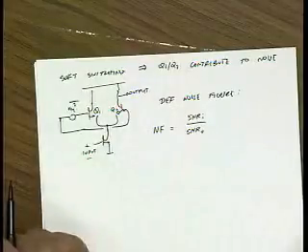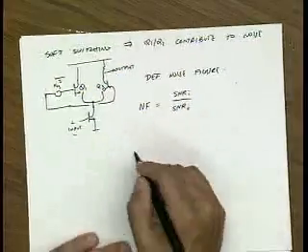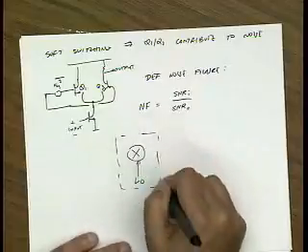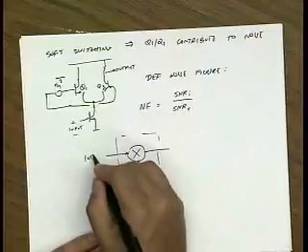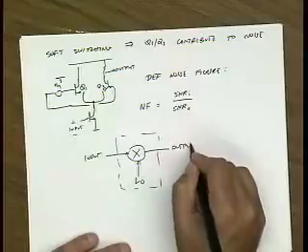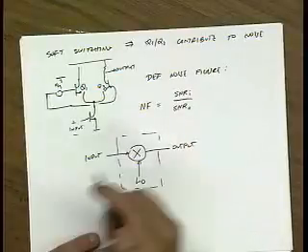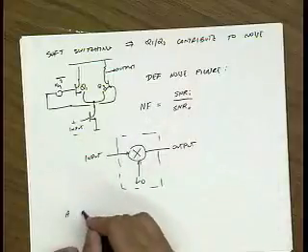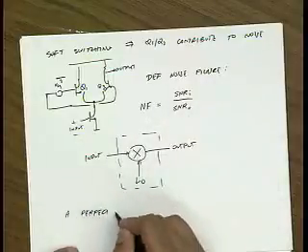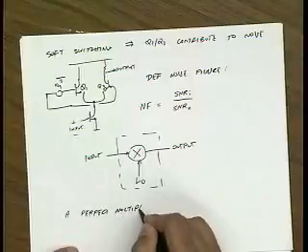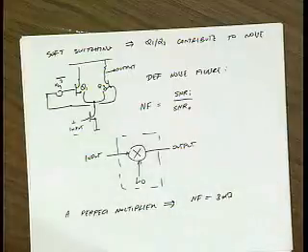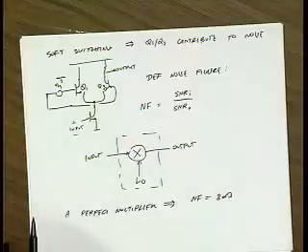The LO is not an input. So the LO is kind of a black box, and the LO is kind of part of that black box. So this is the input, and this is the output. Now, the reason this noise figure definition is complicated is that a perfect multiplier, as you guys all know because you did the homework, has a noise figure of 3 dB because of the image noise folding back onto the same band.